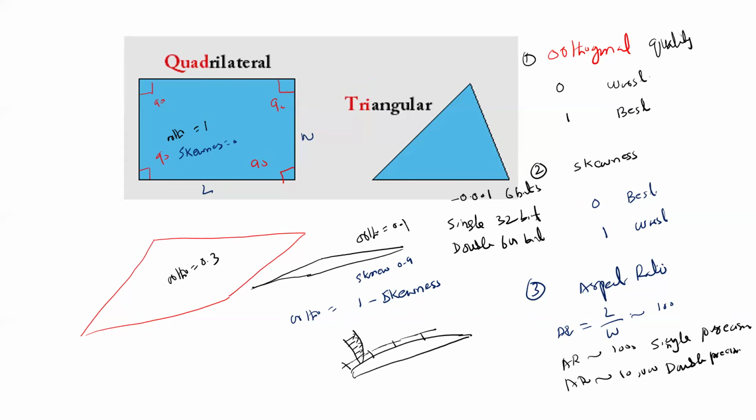But when you change the solver to double precision, it will store up to 64 bits, which requires double the memory. So for the same mesh, because it takes double the size in memory, it will now require double the memory. If we were using a mesh requiring 1 GB for single precision, then with double precision we need at least 2 GB. So now we can go up to 10,000 when we use the double precision solver.